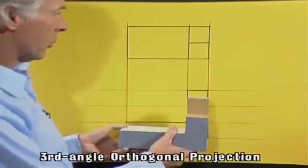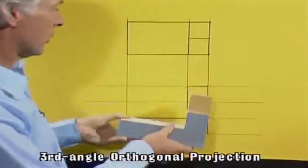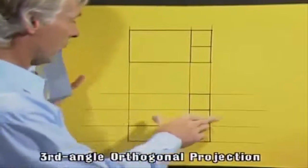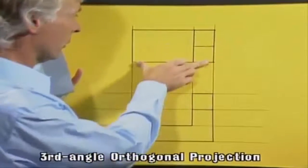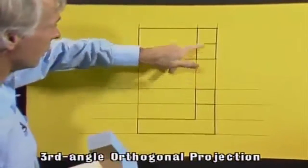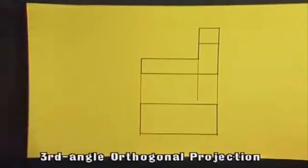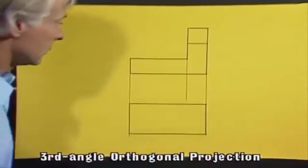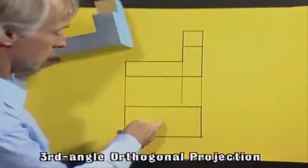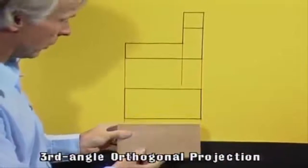Similarly, a top view is shown above the front elevation just by rotating the object through like that. You can see that I've projected the widths from the front elevation up onto the top view. So all I had to measure was the vertical dimensions. A view of the bottom, which doesn't give a lot of detail, is shown below. It's just a case of rotating the model through like that. It's just a straight rectangle.